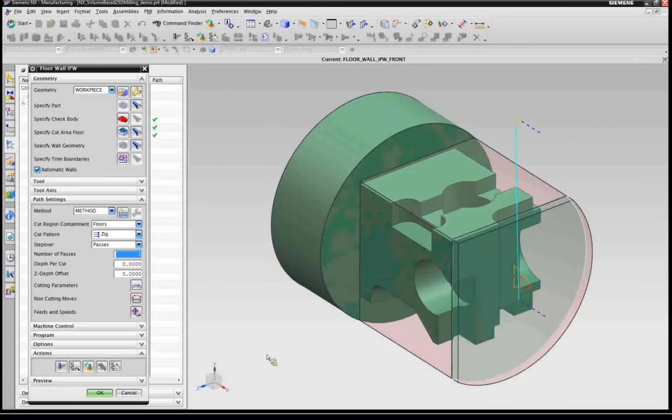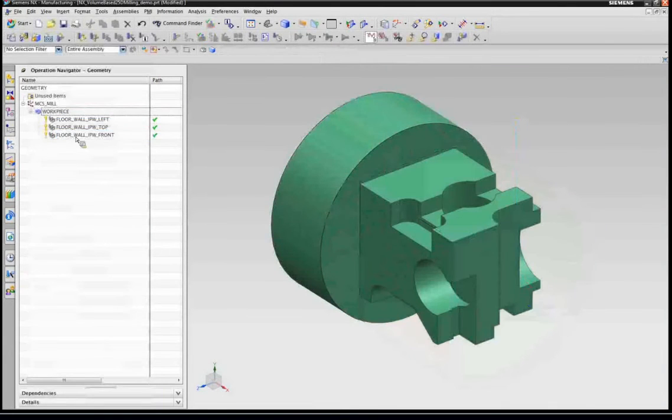Initially, when we were testing this new version, I was very scared because it stops in the middle. And I'm like, it's not even cutting the entire part. This is a bug. But you'll see later on that this is just our attempt to really minimize air cutting. When the tool reaches that point, it has cut all the material. It's a big tool, remember. It's cut all the material that there is to cut on this face, and it can retract. It's done. And we'll see that later. So that's my 3rd operation.